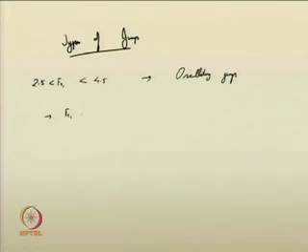For strong jumps, with Froude number greater than 10, the energy dissipation is less. Means if you want a hydraulic jump for dissipating energy, then for higher Froude numbers it is not appropriate, by providing a stilling basin. So, you need to take that into account.